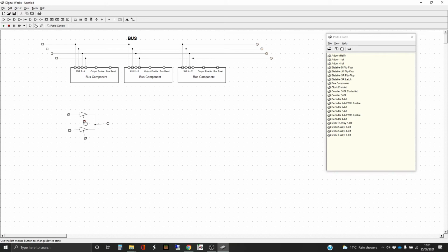So let's disable that one and do as proof the other one. And so if we make changes to here, that's not affecting what's going through. And you see just basically that high stops at the tri-state buffer. And this is the one that's active.